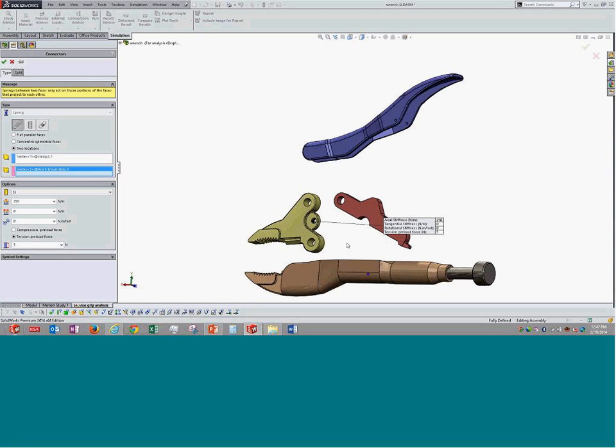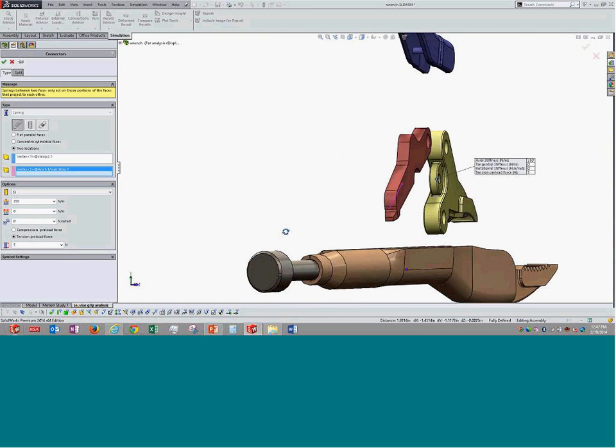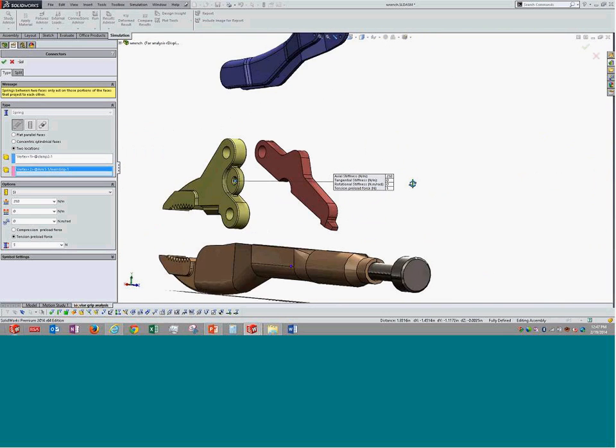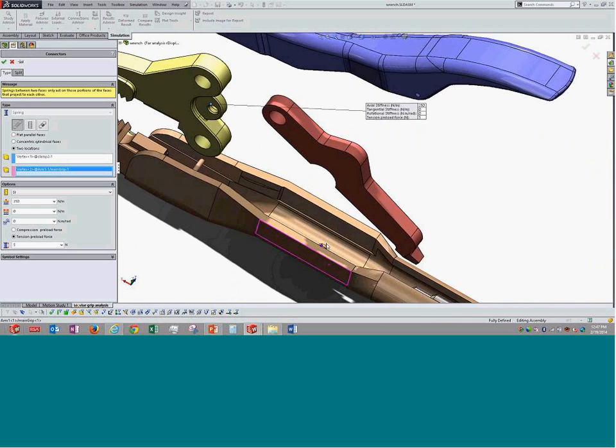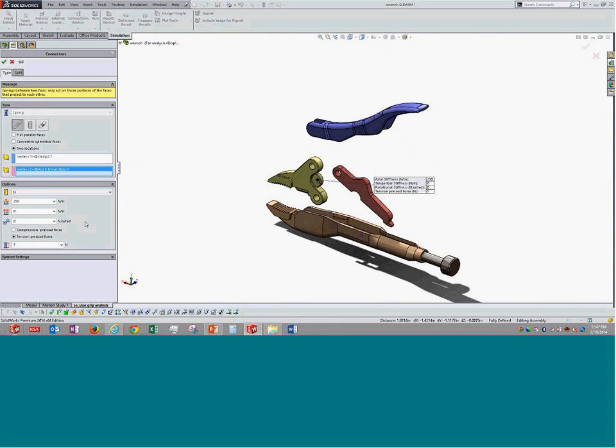So the vertex option or the location option is selected, and we're selecting one point on one part, and on the similar side, one more point somewhere over here. On the second for springs, we can specify the axial stiffness, tangential stiffness, and rotational stiffness if it has any. And from that, it can also have a certain amount of pre-tension or preload, pre-force that is also present, and that can also be defined over here.